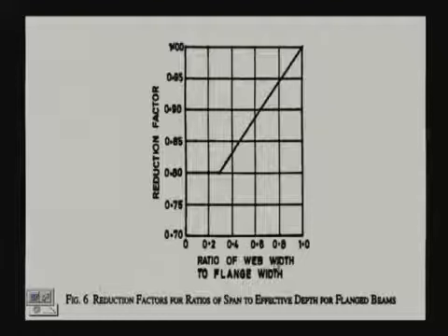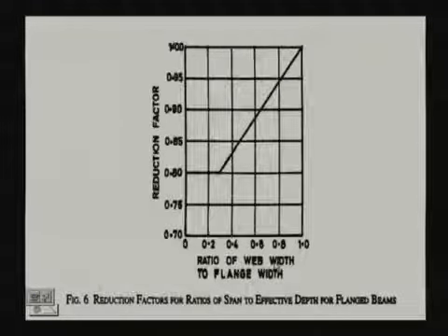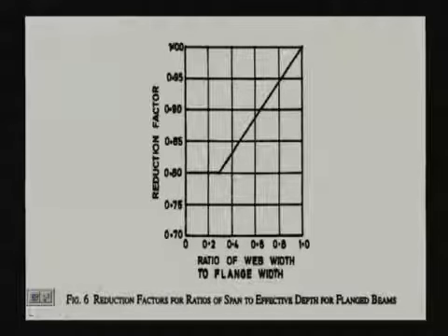So, for slab design or also for beam design, we have to take all those things which I have not given previously, because I thought at least we should concentrate on the formulas that we are using, say Mu equal to 0.138 fck b d squared, like that. And now we are slowly coming to the codes and other things, how to design it. The slab design is nothing but a beam design itself.